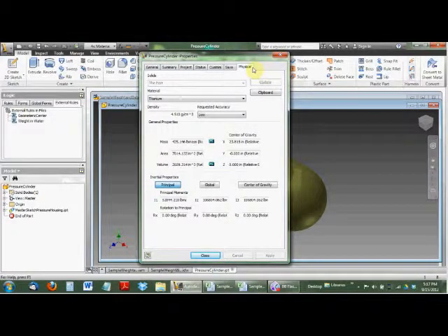When you make a part like the cylinder, it's important to include a material. In this cylinder, I chose titanium. It was already available, and this titanium has a mass and it has a volume, and that's what we're using with our iLogic rules.